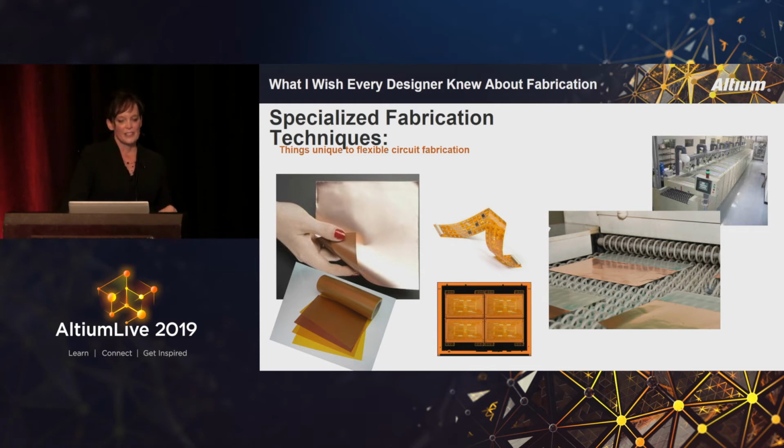I also wanted to talk about panelization with the flex materials. Because they are more expensive and because flex comes in a lot of unusual shapes, it's always a good practice to pay a little bit of attention up front to how you might be able to nest those parts or reverse nest them, L-shaped, anything with a curve. You're able to nest those and get more parts up on your panel. So if you're creating the array, keep that in mind, definitely. Or give it to your fabricator and ask them, what's the optimum way to panelize the board to help bring the cost down?